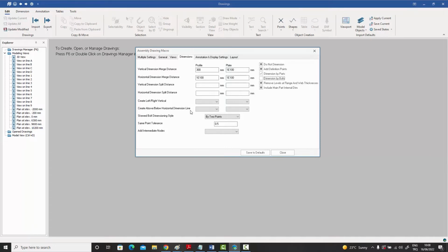So another reason could be that these rolled profiles which are sold in the market, they're sold with certain tolerances. And so the height of an IPE 300 beam, when you actually go and buy it, might not necessarily be 300. It could be 299 or 298.5.